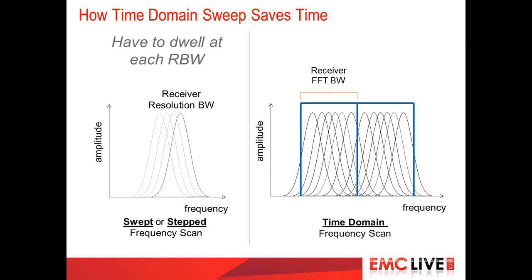On the left is traditionally how measurements have been made, swept or stepped. You can see the outline of the resolution bandwidth filter. For each frequency point, we're dwelling on an order of milliseconds, but for several thousand points, that time starts to add up very, very quickly. So think of this as serial processing, one point at a time.